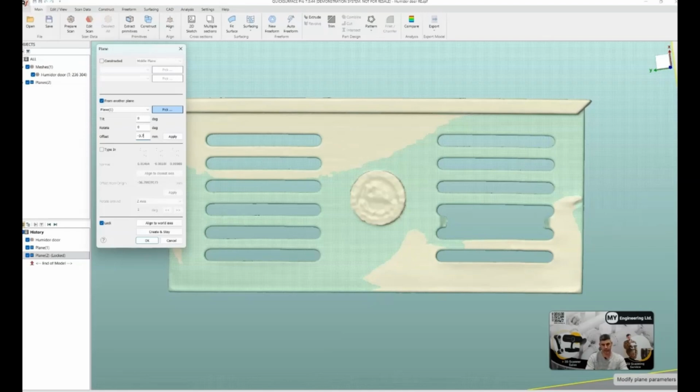Because we know that's what's actually going to fit into the slides where this humidor little door actually fits into on the body of the humidor. As you recall, when we started this, the whole issue that we ran into was a little bit of moisture got into this sort of cardboard wood product. It swelled, it got stuck into the grooves that it slides into, and while trying to remove it, it ended up breaking. So we want to make sure that it is going to be the nominal thickness, and so I use the calipers to determine 3.7 is the right number.